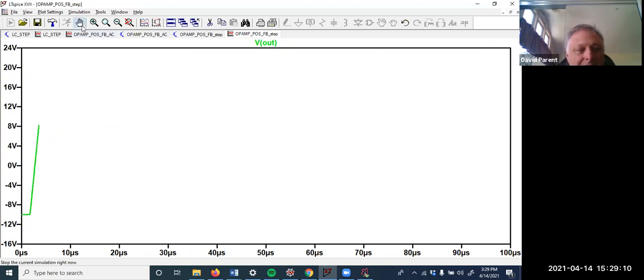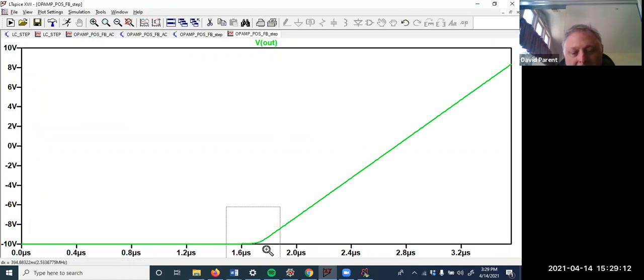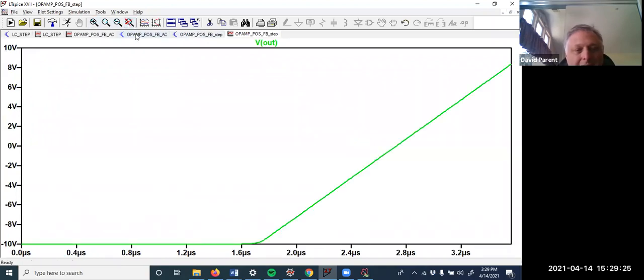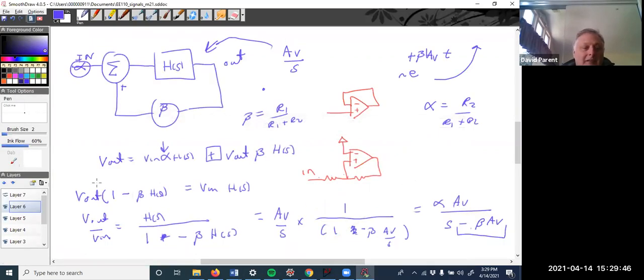And I'm just going to stop it. In fact, you can start to see the exponential growth there. Why is it turning into a straight line? Well, op amp output voltages can only change so fast, and that's a limitation that you'll learn about in 122. But there's that exponential growth there. It's positive feedback.